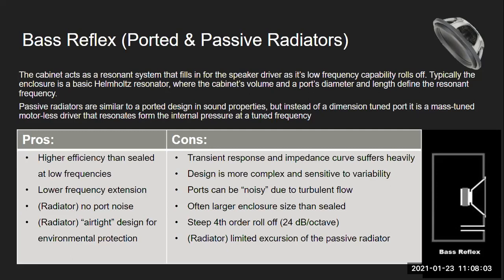But what it is, instead of using a port, you just use effectively a speaker driver without the motor on it. So you have a mass and spring system, and a little bit of damping as well. But it's just a basic resonant frequency calculation. So you've got your spring constant K and then your mass, and from that you can calculate your resonant frequency.